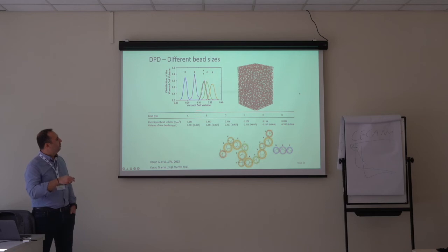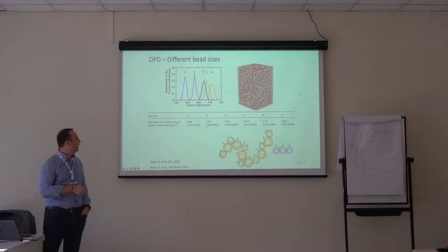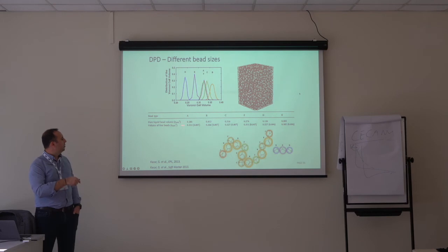But for the rest, when we look at the real epoxy system, the beads are, of course, separated from each other, so we employed at that time the Voronoi tessellation and then observed the local densities around beads, and we see that from the experiment.